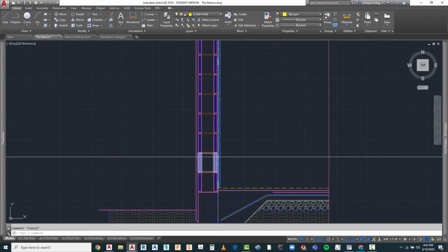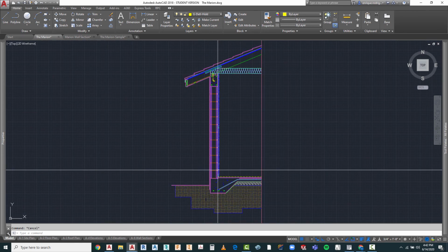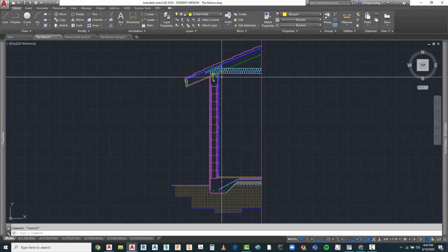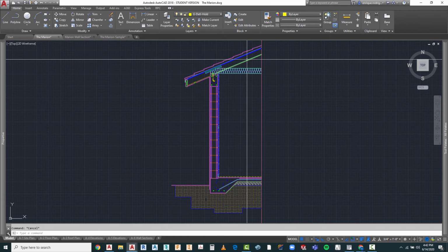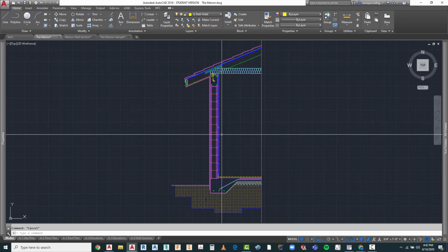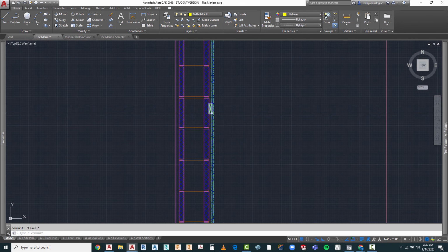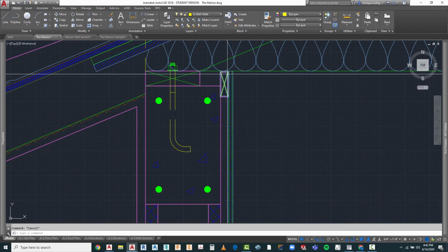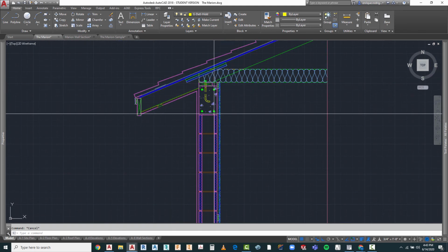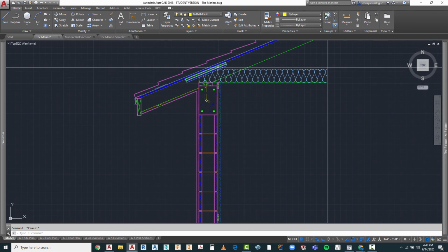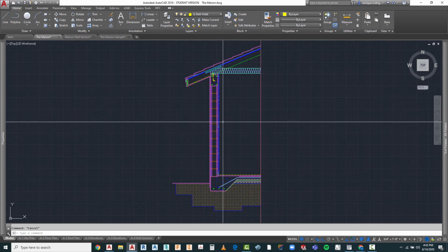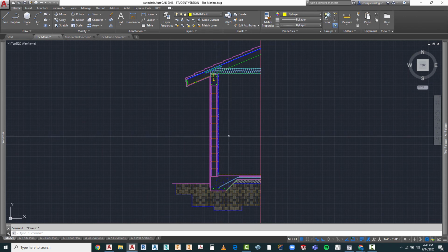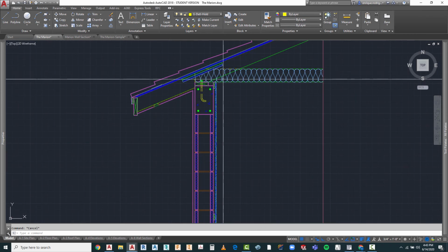So if you have a short circuit in one of the boxes and it starts a fire, rather than going immediately up through here and into this fuel-rich environment of the wood trusses or rafters in this case, this won't stop it, but it'll delay the fire from spreading, including the smoke, etc. So we have one at the top here, always at the transition between the wall and the ceiling or roof, and then the other one, depending on the height of the wall, you may require an intermediate fire stop in between.